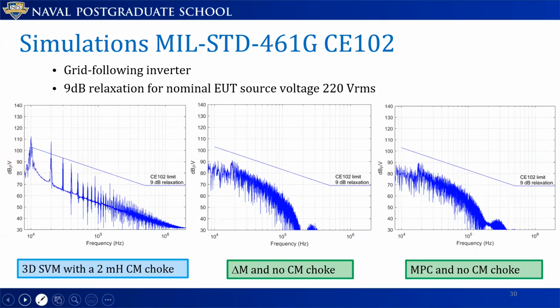This 3D space vector modulation is the classic one, right? There was a paper from Virginia Tech from 2002, I believe, that is cited in all of our papers. They're not trying to cancel common mode here. A few later papers did try to do some common mode cancellation in 3D space vector modulation, but we're just using the standard. So there is no attempt to cancel the common mode here, and so you need a large common mode choke. That's why our LISN are rated for low power, and why we haven't even attempted 3D space vector modulation without a common mode choke.